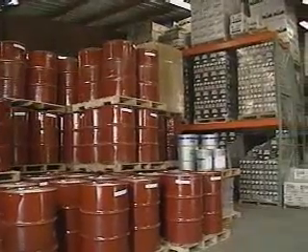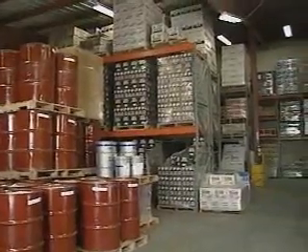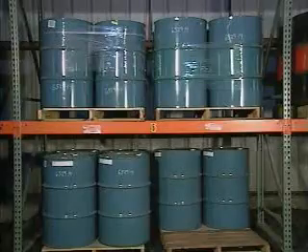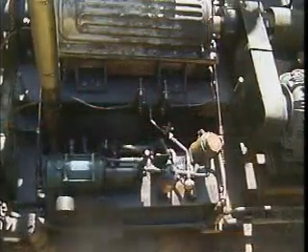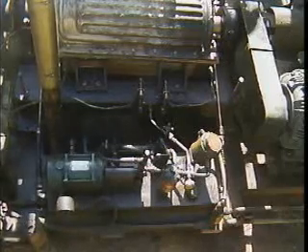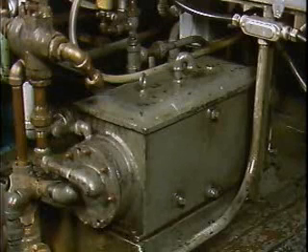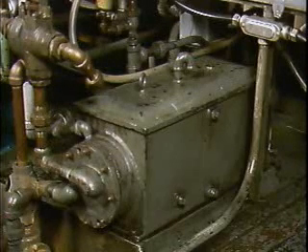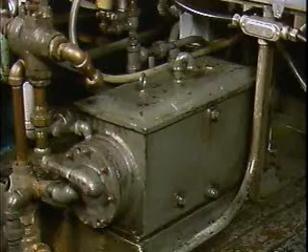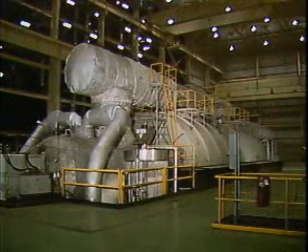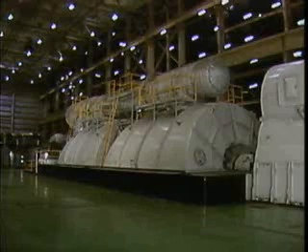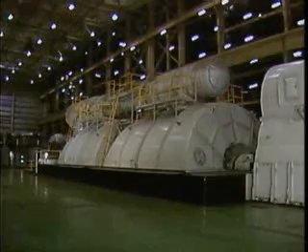Oils are often divided into several common groups based on the uses for which the oils are suitable. One group of oils is circulating oil. Circulating oil flows or circulates through a piping system or moves freely within a closed area. The circulating oil group also includes hydraulic oil. Hydraulic oil is primarily used to transfer force from one component to another in a system. Sometimes, though, the same circulating oil is used for both lubrication and hydraulics. For example, large steam turbines are often built to use the same oil for lubrication and for hydraulic control.